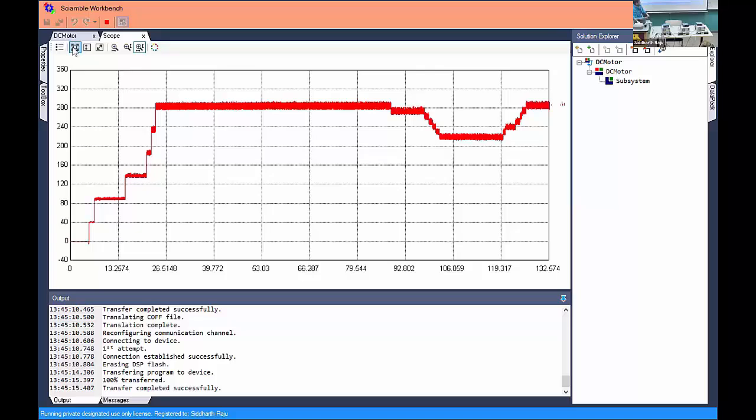Why the torque? You're drawing more current, so it's taking energy from... It has to decrease. I see. Right? It's creating a back EMF that takes away from the voltage being applied to the motor. Right. But once we get to a particular speed, the back EMF is a constant. Right.